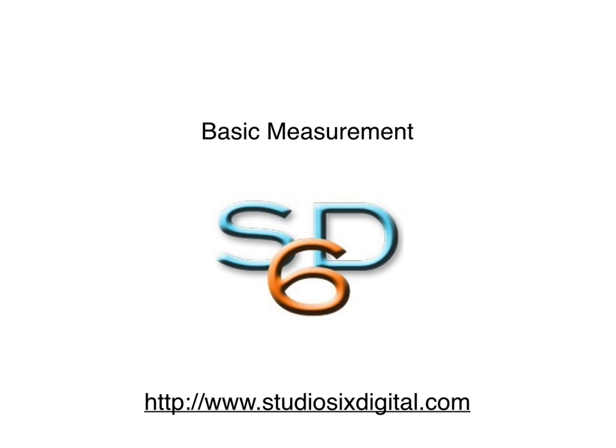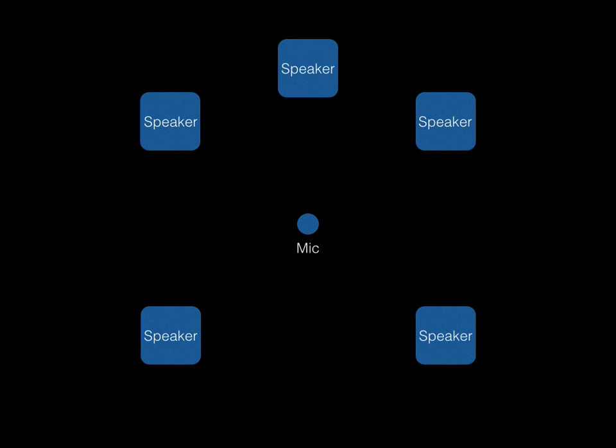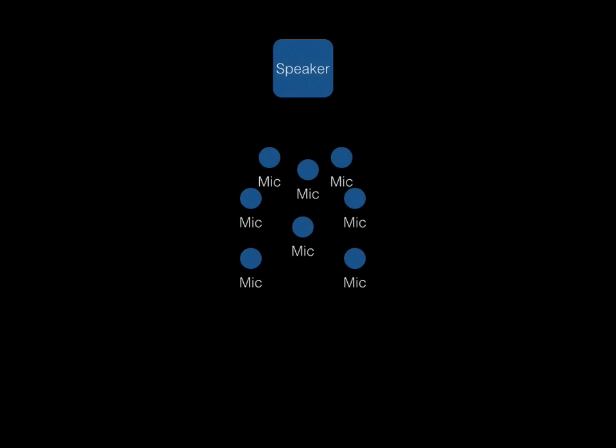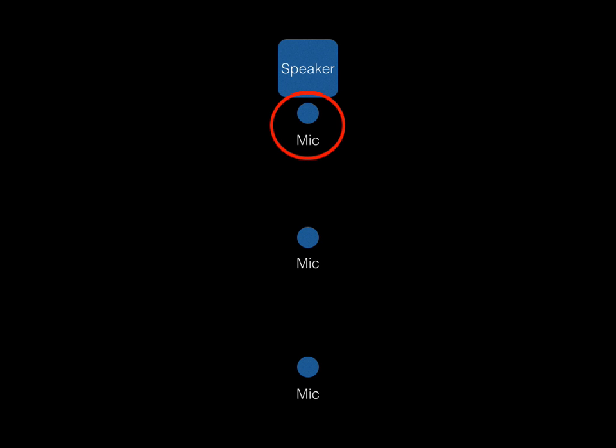There are two basic ways to use LARSA. The first is to make individual measurements of different loudspeakers or measurement locations around your room. The other is to make multiple spatially averaged measurements of the same loudspeaker. We will start with the first case where you wish to measure, for example, a small studio monitor in 1, a close microphone configuration, 2, at the listening location, and 3, at a location in the diffuse field.